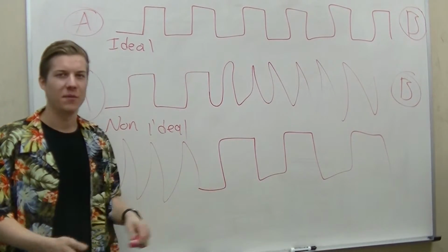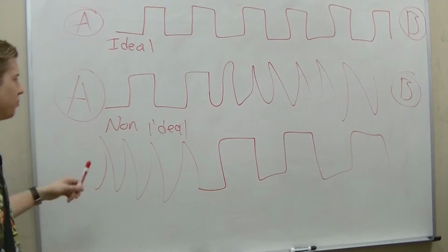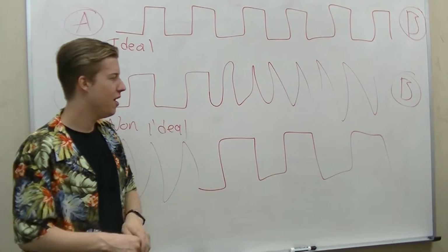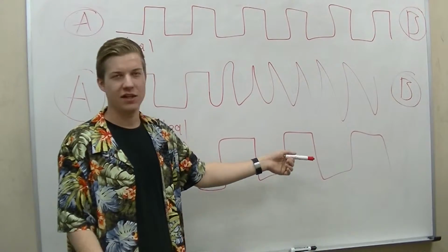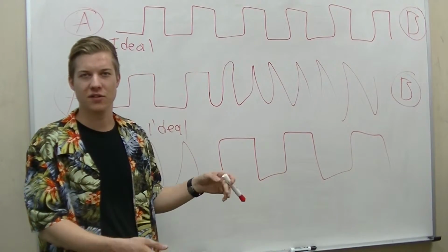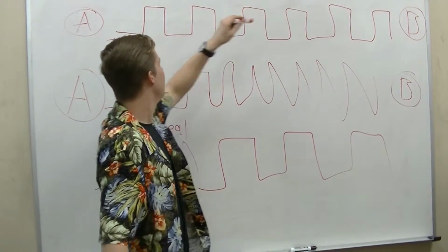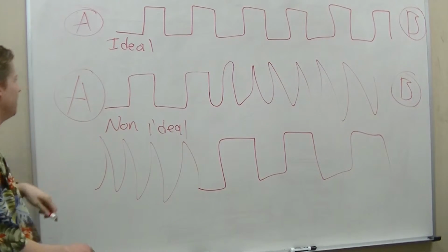One of the things we wanted to talk about were recovery methods. So one of the things you can do to your signal is pre-distort it. Because the distortion comes after it goes through the entire line, we pre-distort the signal. That way, after it goes through the line and gets all the distortions, it's actually distorted into what it's supposed to be. So like an ideal line, we have our ones and zeros, and they're nice, squared off at the leading and the falling edge.